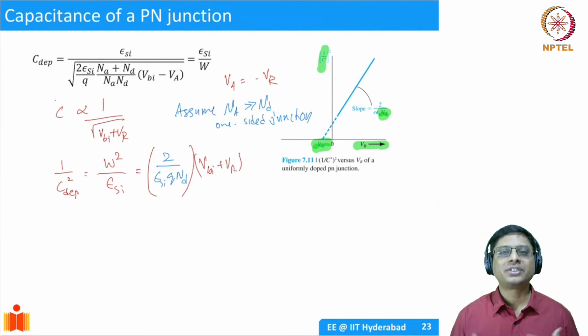If I do that, the capacitance is going to be large, and because of it, it's going to be slow. This is one of the reasons why semiconductor devices, over the last 50 years, have been continuously shrunk in size. So much so that today we have MOSFETs in 5 nanometer or 7 nanometer technology. They are very, very small devices. The reason is that once you make it smaller, the capacitance reduces, RC reduces, so that circuits are faster. That's one of the primary driving forces.